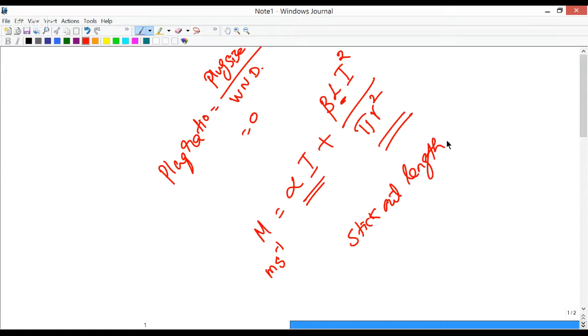Assignment 3, question 8. When the welding current is increased above spray transition current in GMAW, that's what we discussed in detail, spray transfer occurs. And assignment 3, question 9. In cold metal transfer welding, the primary metal transfer mode is... that is a very straightforward question, because cold metal transfer welding is developed with respect to the short circuiting transfer. And assignment 3, question 10. In pulse GMAW, which transfer is promoted? Okay, drop transfer is promoted.